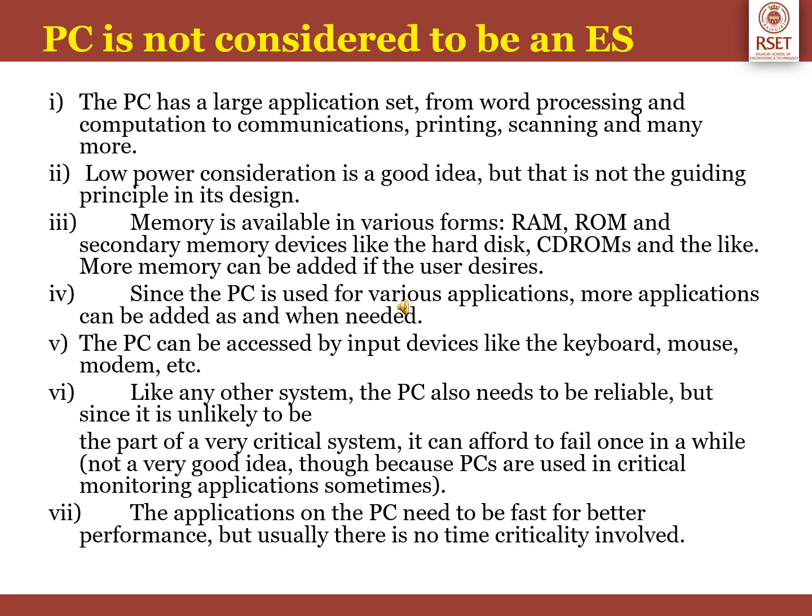The personal computer, PC, is not considered to be an embedded system. The reasons are: the PC has a large application set from word processing, computation to communications, printing, scanning, and many more. Low power consumption is a good idea, but it's not a design principle in its design. Memory is available in various forms like RAM, ROM, secondary memory devices like hard disk, CD-ROM, etc. And memory can be added if the user desires.